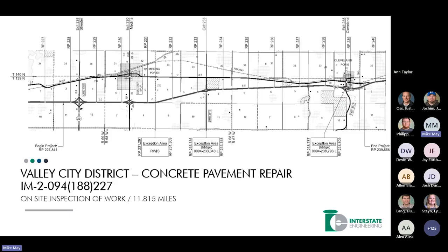On the driving lane, there was actually a CPR dowel bar retrofit done on it. And on the passing lane was just solid 10-inch poured-in-place concrete pavement. No dowels or nothing. So a lot of stress. There's a big hill in the middle, a lot of stress coming down. I'll talk about that in a minute.